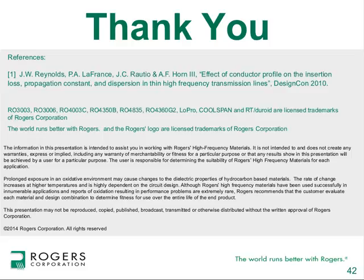Okay. What frequency is the 6035 insertion loss specified? That would have been 3.3 gigahertz in this presentation, even though I've done testing all the way up to 50 gigahertz on that material. But for this presentation, it was just at 3.3 gigahertz.